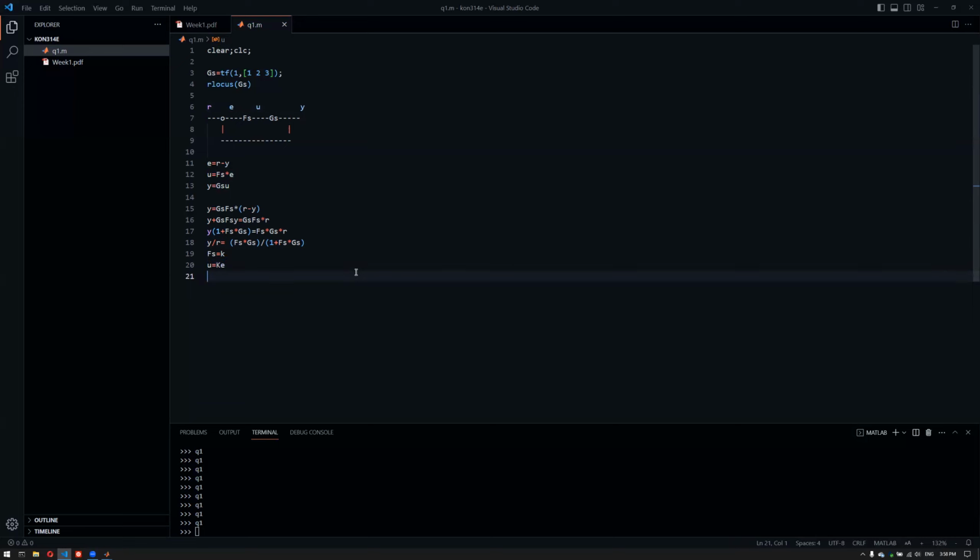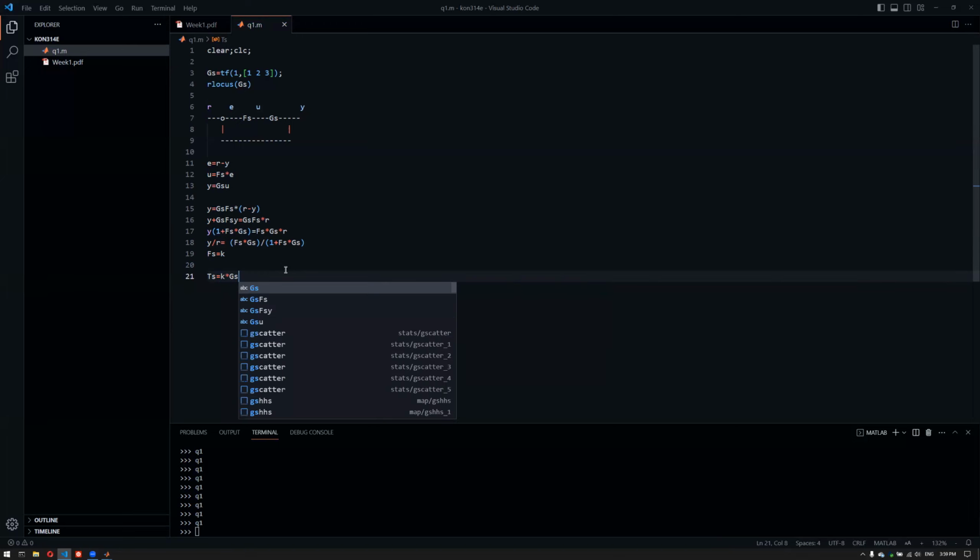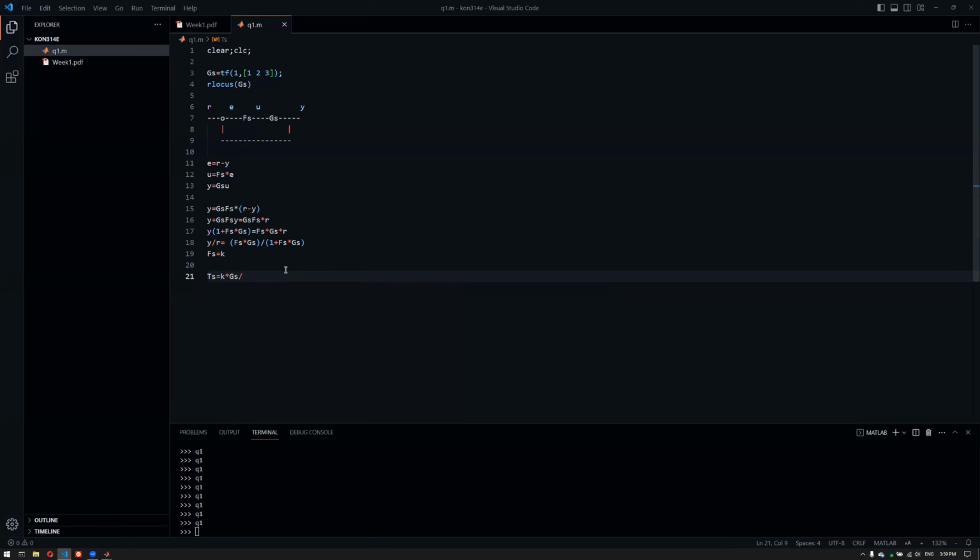We will be considering the PID controller in the future. So proportional, integral, and derivative parts will be combined into the PID controller. So you have to know the P-type controller quite well to understand the PID controller even better. So when we plug in this one here, what we get is basically K times C(s) divided by 1 plus K times C(s).